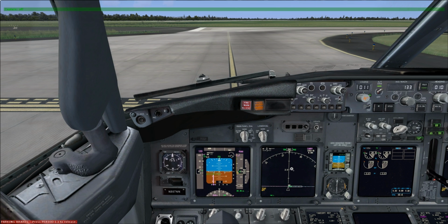The 2 types of wind shear that I know about are the ones with a rapidly changing wind speed and or direction, usually associated with terrain, and the microburst, which is the type of wind shear that I'm going to focus on today. Microbursts are usually associated with thunderstorms and virga. And to get an idea of what I'm talking about in relation to microbursts,